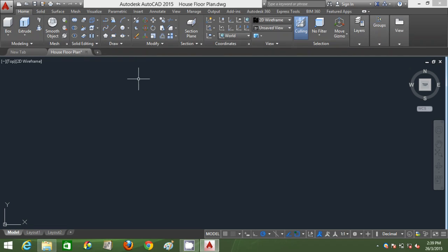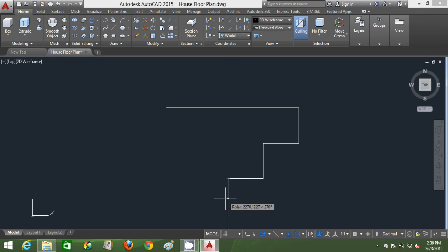So we'll be starting in drawing the floor plan layout. I'm going to draw this 15,000 mm line. And this wall is measured 4,000. And over here is 4,000 also. This one also is 4,000. This is also 4 meter, along with this wall. This wall is 5 meter, 5,000. So I can use my object snap track to complete this floor plan layout.